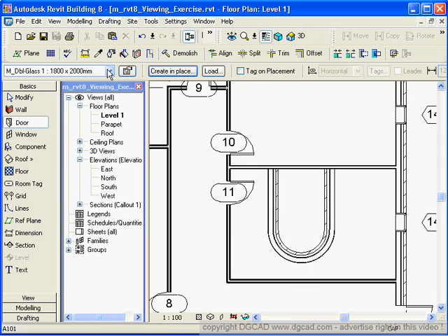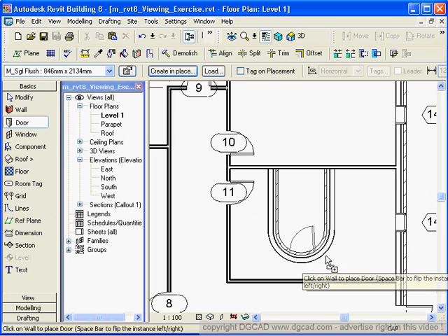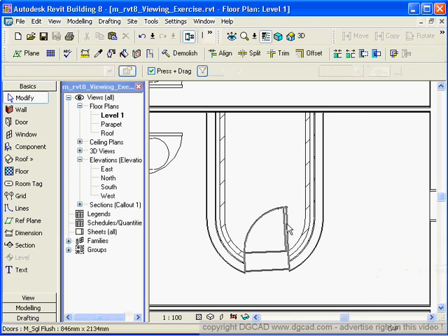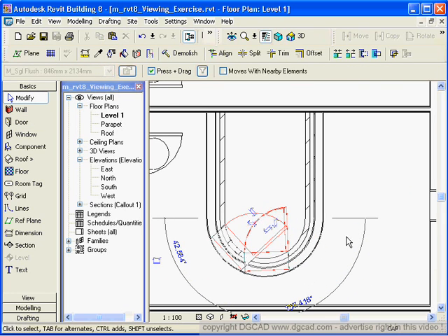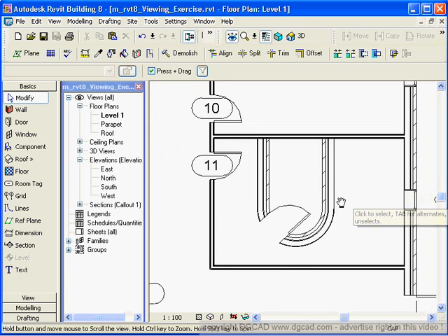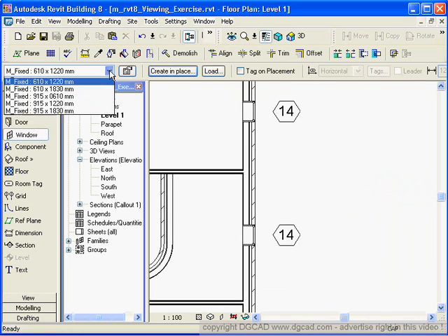You can also go in and put a door. We'll talk a little bit about doors. Go to a single door, add a door inside of there, no problem placing the door in the arc, and we can take that and we can move that around. Not a problem in rounded walls. Okay, and then we can place windows. We can go in and grab a window.